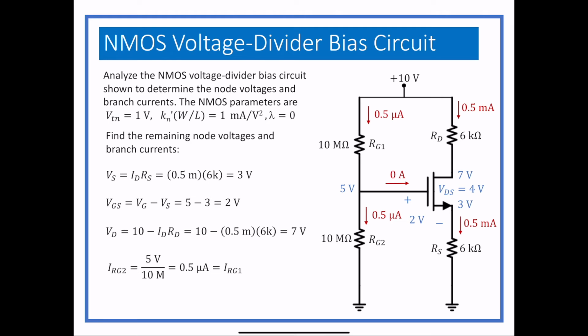Usually those resistors are large, and the reason is that when you start inputting a signal into an amplifier, you want the input resistance to be as big as possible. You remember we covered that a while back. While the input to the gate is infinite, those resistors are going to have some effect. So we just make them large, and that works just fine.